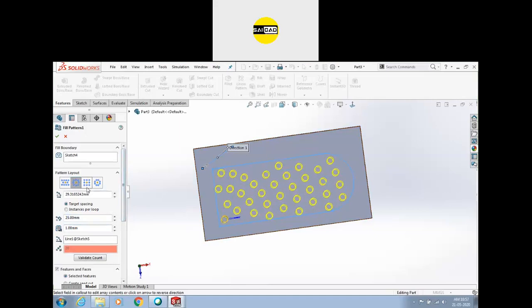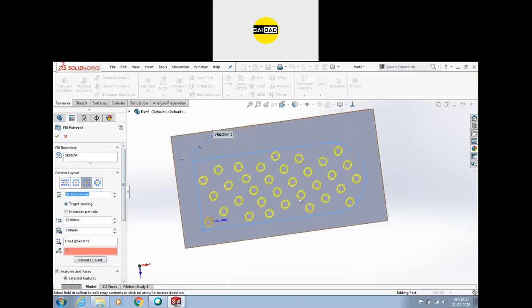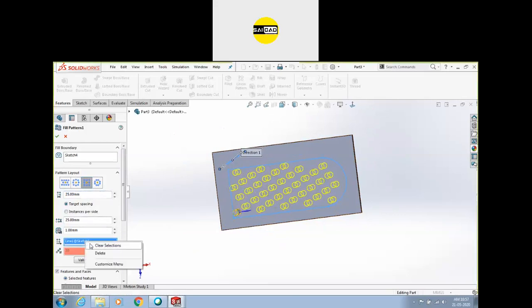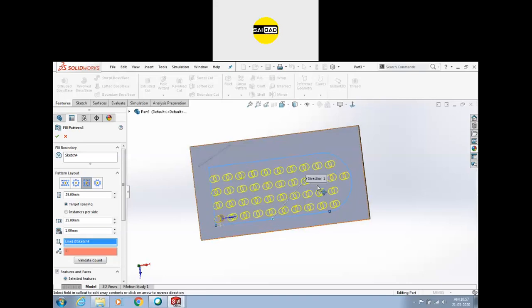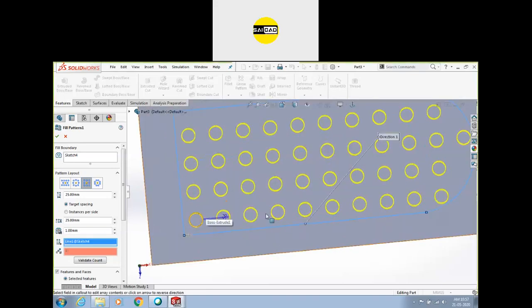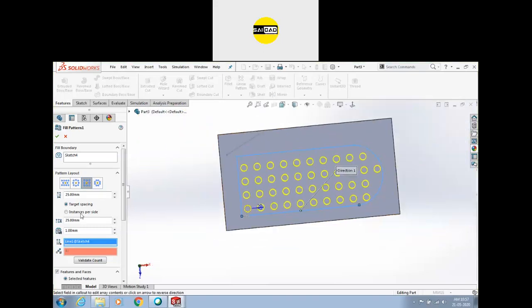Okay. So after that we have an option square. We can create them in the square option, the square shape. So you have to specify the gap between two objects. I want that gap to be 25, and right now we have selected a reference line. Clear that, select the reference. So you will see that objects are being created in the square direction. You can see that those are in straight rows and columns. Okay, so between gap is from here.